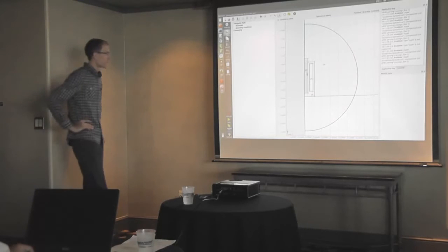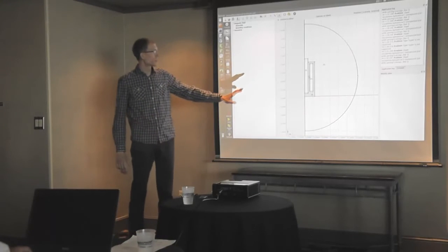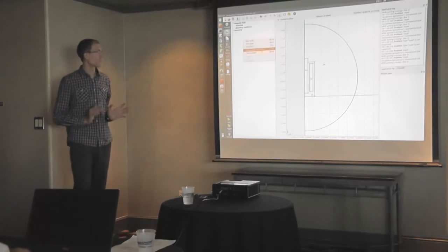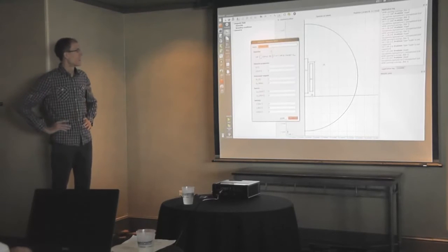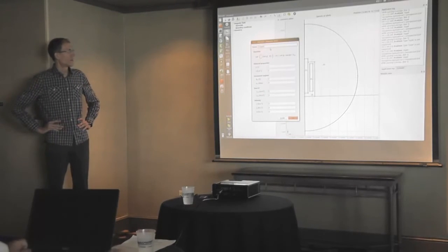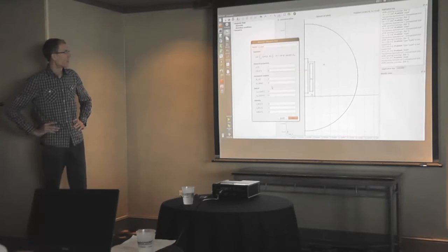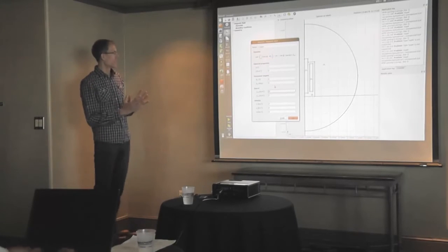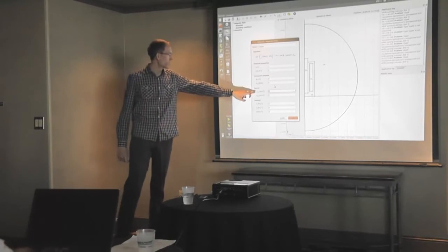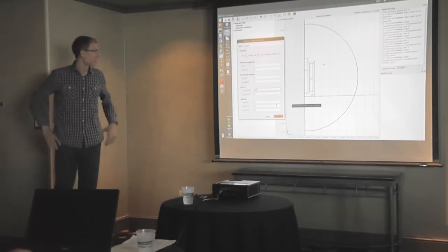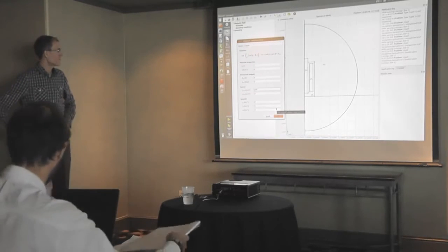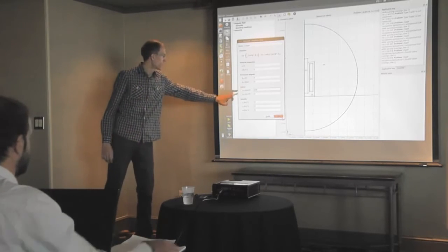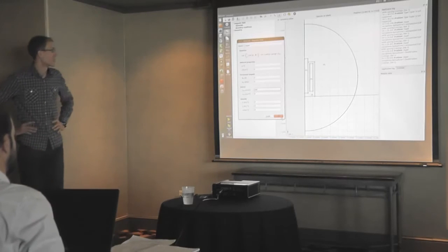Now we are putting material markers, so each area has a different marker. We will use it for the definition of fields later. Now we have to define materials. So we have copper, which is used as an inductor, so we prescribe external current density. Of course, it's a harmonic field, so we have two of them here, real and imaginary component.